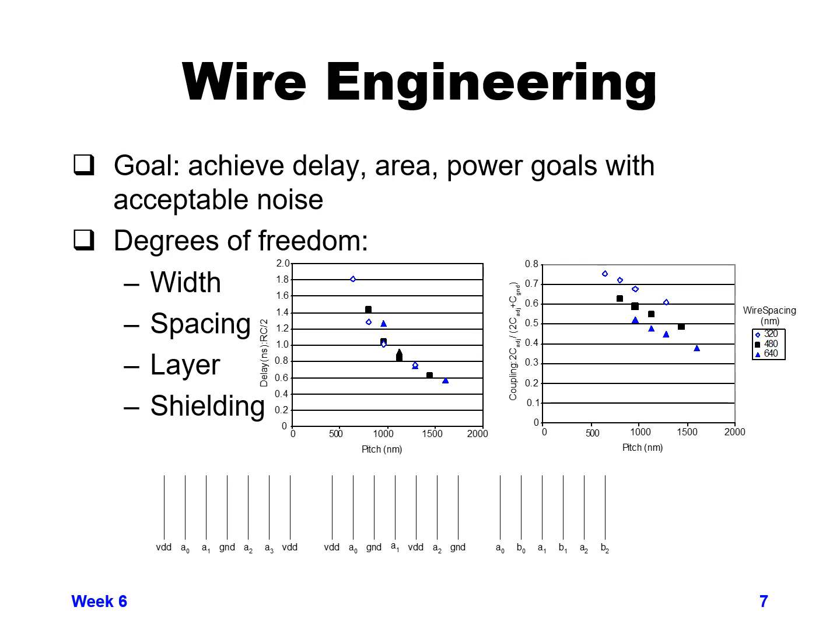So in the lower left we can see some tracks where we have VDD and then A0, A1, and then a ground wire, and then A2, A3. So each of the A wires is always next to a constant, either VDD or ground, and only next to one neighboring wire that can switch.